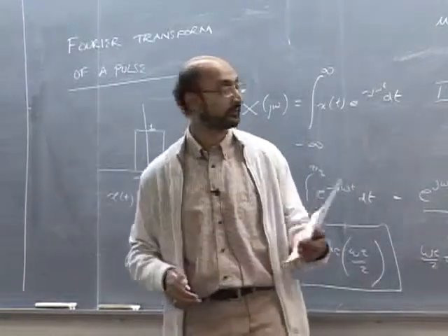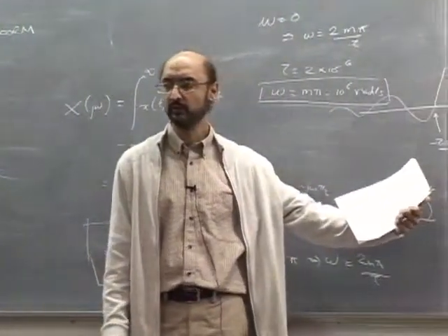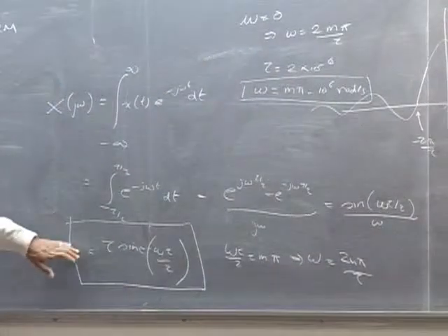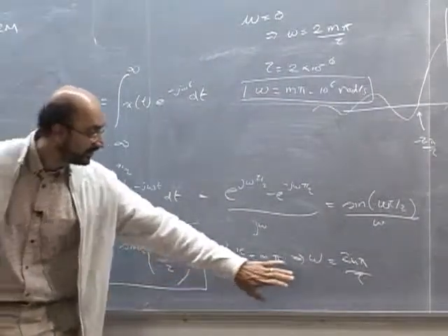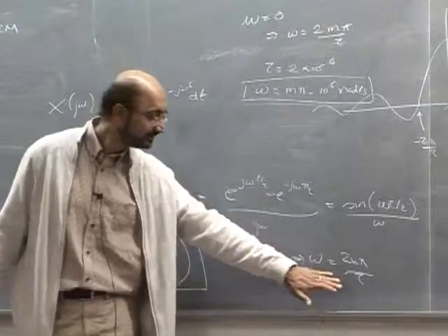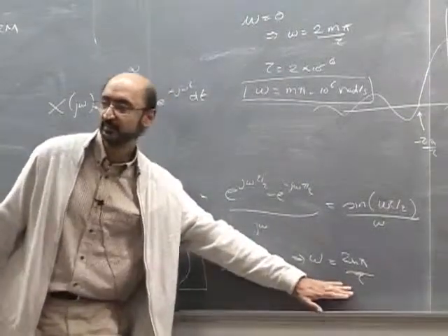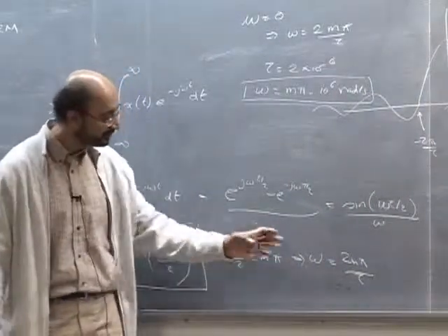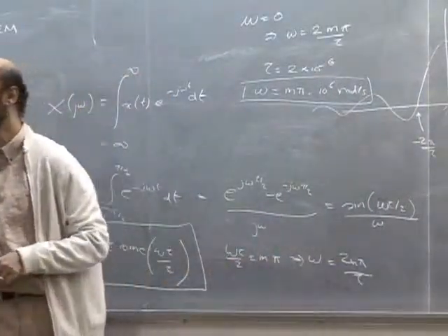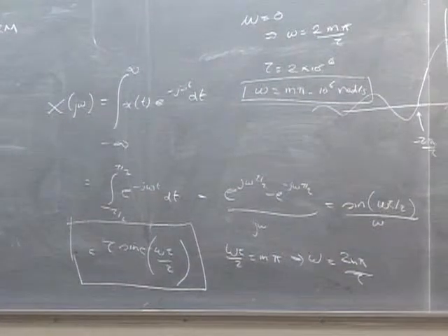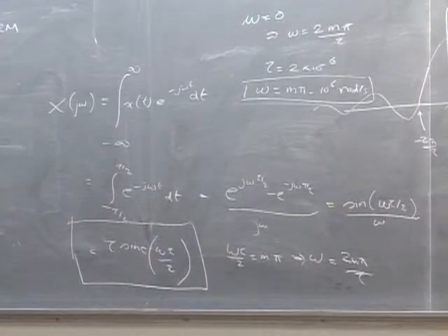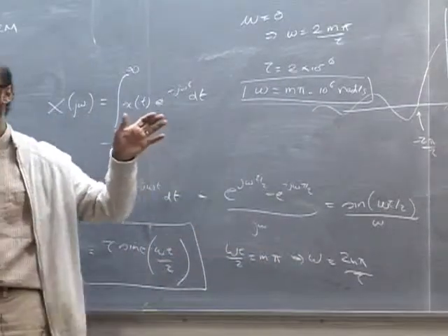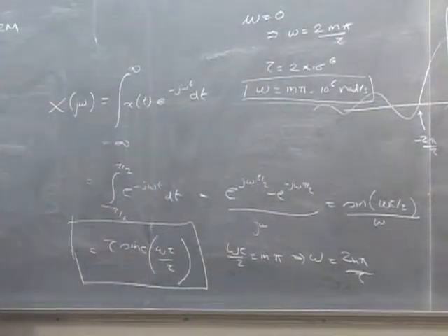And that's why we have this over here, OFDM, and that comes from the nice property of the sinc function that it has zero crossings at 2m pi by tau. So this little equation over here is worth billions of dollars. It's not as good as E equals mc square, but omega equals 2m pi by tau is pretty close to it. Okay. And that's what everybody uses today. OFDM is the thing. So this is how math relates to communication and relates to what happens in the real world.